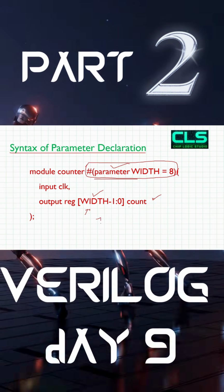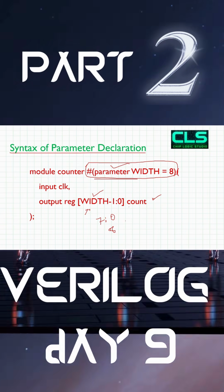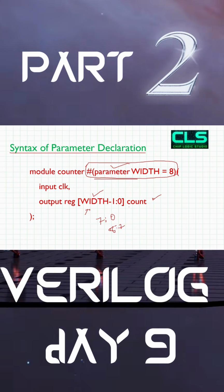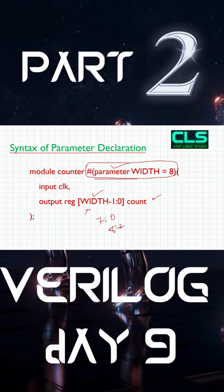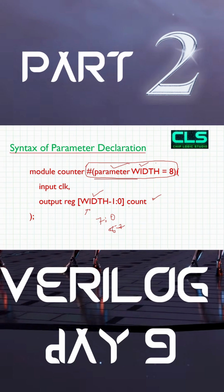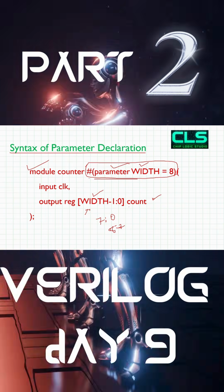-1 is like, for example, if it is 7:0, it means total size is 8-bit. So this is width -1: 8 - 1 is 7:0, and you will get your count as 7:0, 8-bit. And whenever you want to change the value of this width parameter, I will tell you two ways to do it without using the actual module. We will change it with the help of the testbench. Okay, so this is the simple syntax.